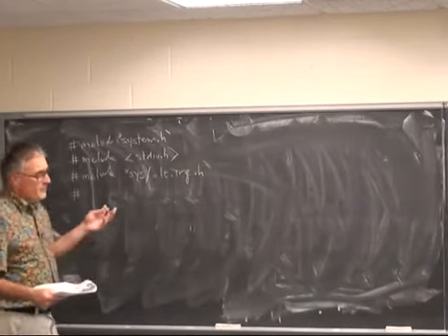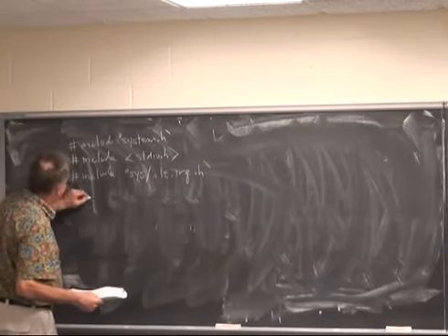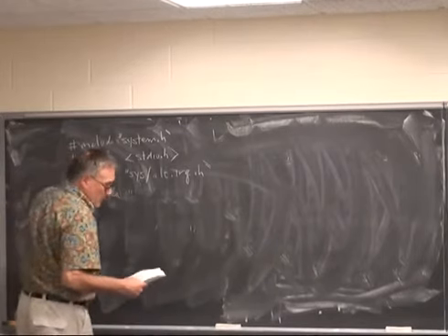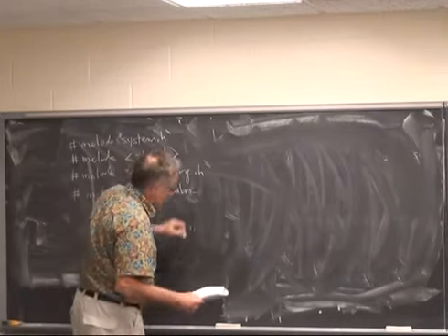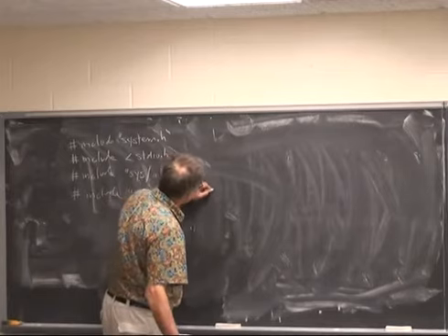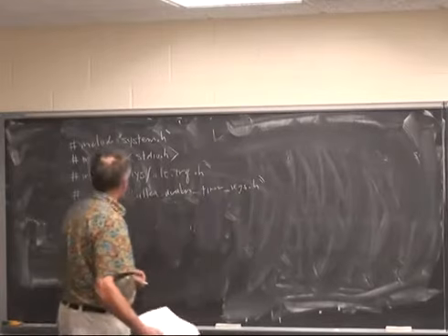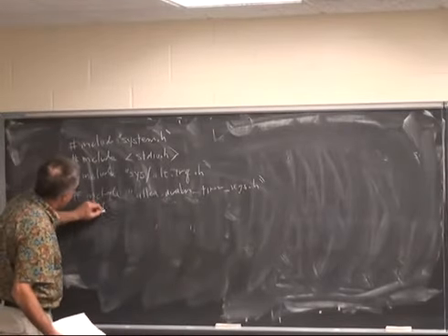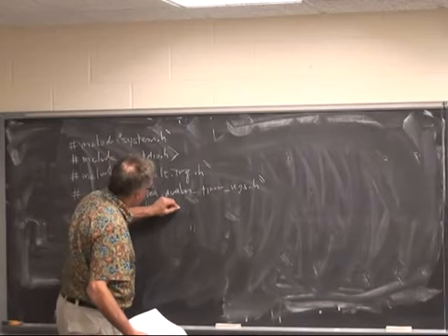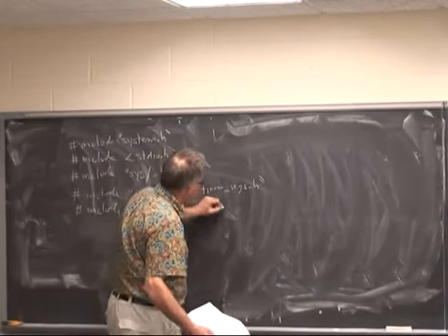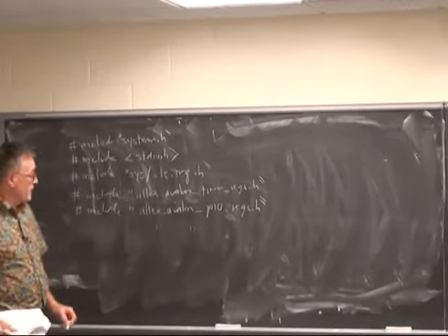And then, because I used the intermediate level I/O macros in this example, I had to include Altera Avalon timer reg.h and include Altera Avalon PIO reg.h. These names are astonishingly wordy, as you will see.